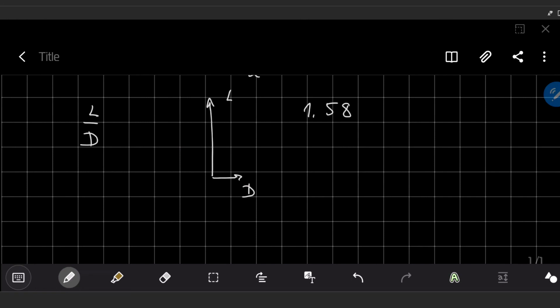And this nice airplane has a CL coefficient equal to 0.15, and it has initially the drag coefficient CD equal to 0.0169. So the lift to drag coefficient ratio here is a bit smaller than 10. Quite a good lift to drag ratio.